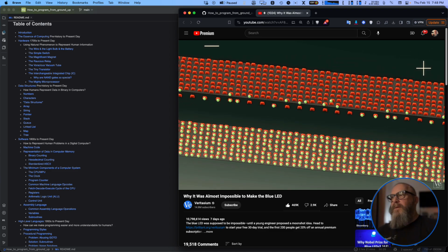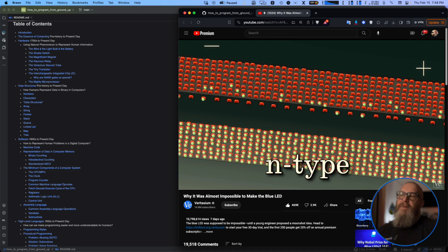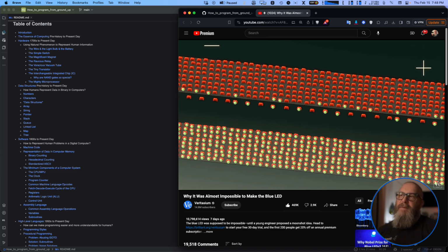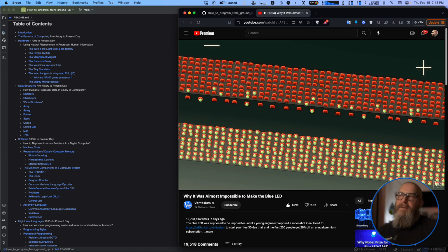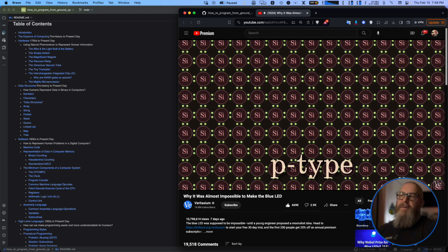Since most of the charges that can move in this type of semiconductor are electrons, which are negative, this sort of semiconductor is called N-type, N for negative. But I should point out that the semiconductor itself is still neutral. It's just that most of the mobile charge carriers are negative. They are electrons. So there is also another type of semiconductor where most of the mobile charge carriers are positive, and it's called P-type. To make P-type...